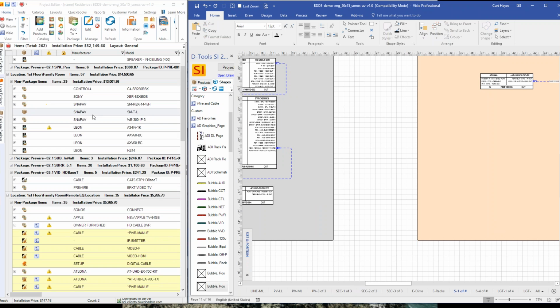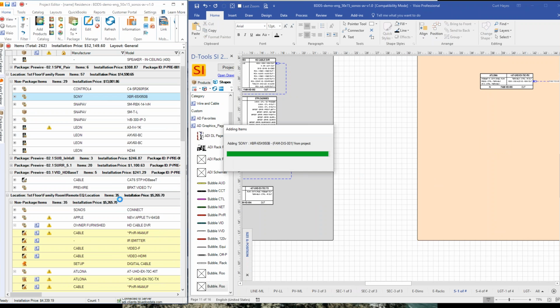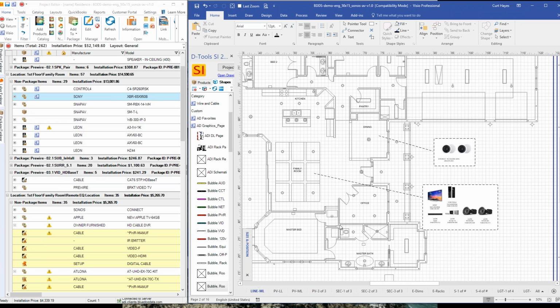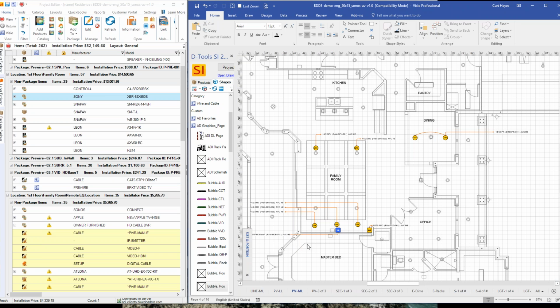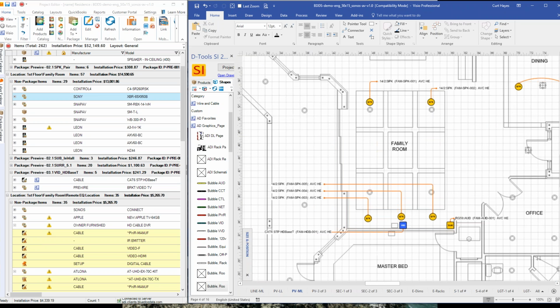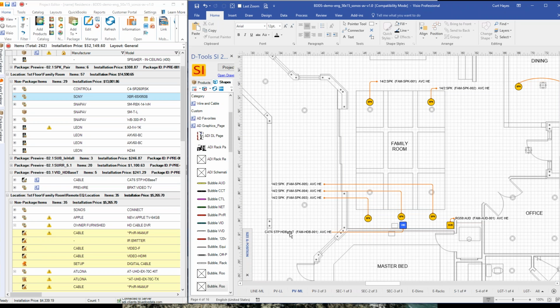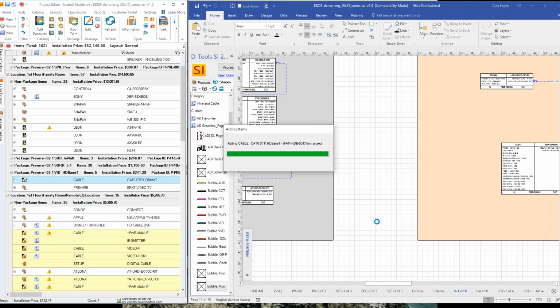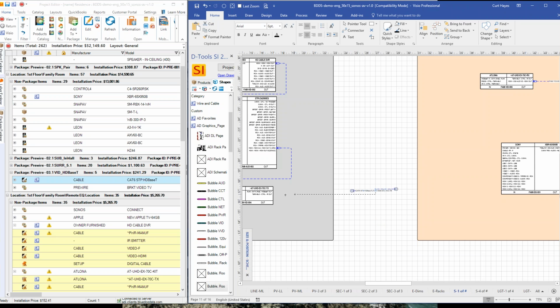And we'll get our TV now. So we've got a Sony up here. And if you recall, back over on our plan view page, wherever plan view was, here it is, I've got a Cat 6 shielded twisted pair for HDBaseT. So now I can leverage that in my schematic drawing. That's going to be right here. Go ahead and pull this in, and this lets me make the connection across the building basically.